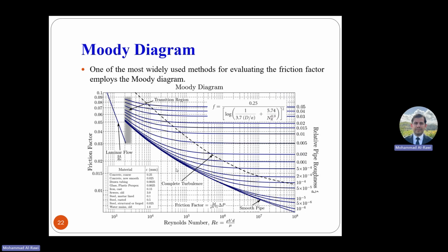So you come here, you intersect with the blue lines, and then you read from the other side, on the y-axis, the friction factor. Now, in MATLAB last time, when you did MATLAB with me in scripting and applied computation modeling, we used this equation for the friction factor F. This equation is based on this experimental data. I strongly recommend you use this equation. You just set it up in an Excel file to perform your design, because you don't want to use the chart every time since you're doing a design problem.